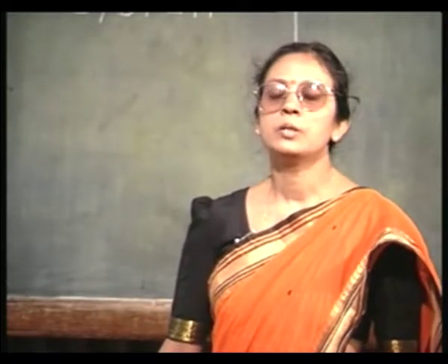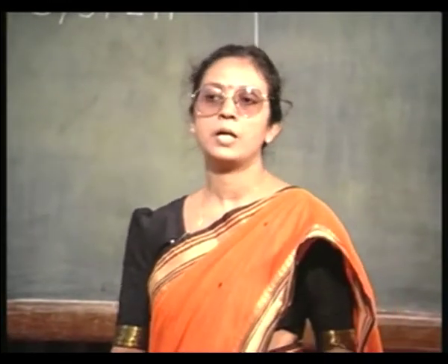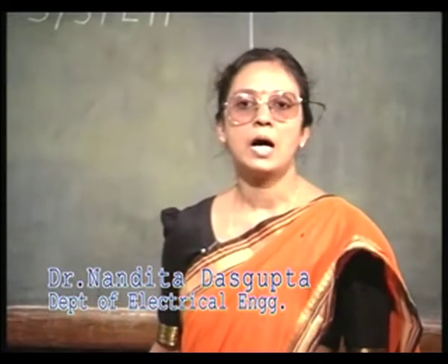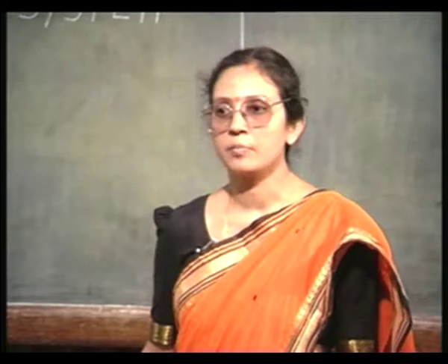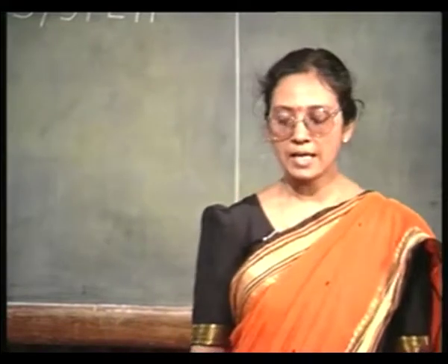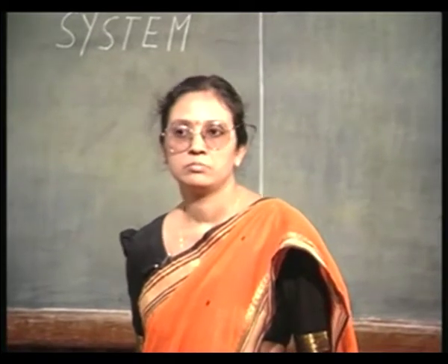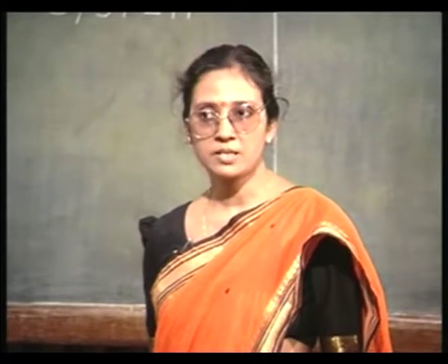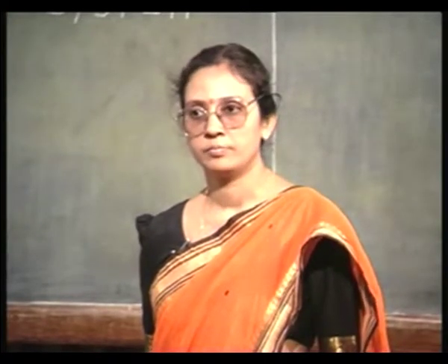Okay. Now, let us come to the actual ion implantation system. What are the different parts in that ion implantation system? How exactly does it function, and how do we really control the dose by varying the parameters of the implantation system? So, first of all, in an implantation system, the first thing that is needed is an ion source. We must have a source for the dopant and it must be ionized, right.